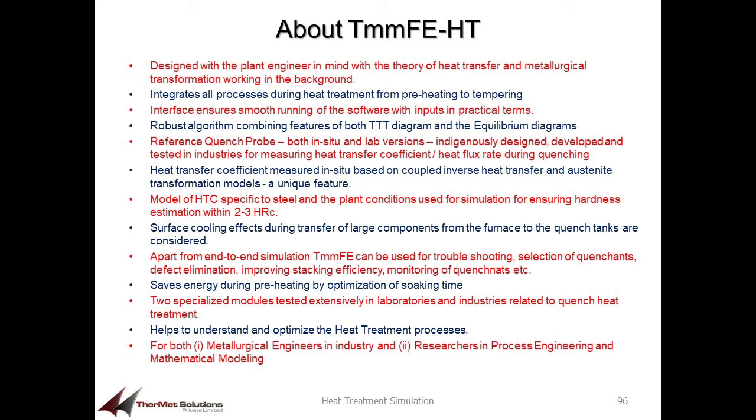Reference quench probe, for both in situ and lab versions, is indigenously designed, developed, and tested in industries for measuring heat transfer coefficient and heat flux rate during quenching. Heat transfer coefficient measured in situ based on coupled inverse heat transfer and austenite transformation models is a unique feature which we offer. Model of HTC specific to steel and plant conditions used for simulation ensures hardness estimation within 2 to 3 HRC. Surface cooling effects during transfer of large components from the furnace to the quench tanks are considered.